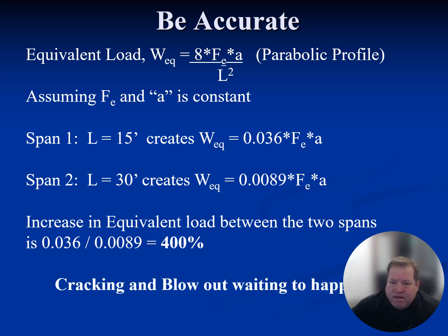You have to be diligent because, again, the force in the strands is always present. It's just not going to be there for life safety applications. Now, having said that, I don't mean to design slabs for every foot they change L. Typically, I'm 3 or 4 feet, 5 feet on center. But if you go back to my previous slide, there's a cascade effect because I want to match the weight of concrete that those tendons are affecting. And so I don't create bad situations by just being grossly conservative.